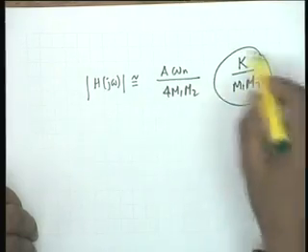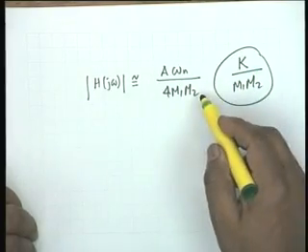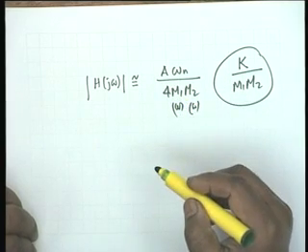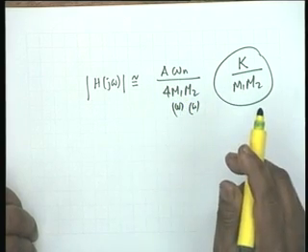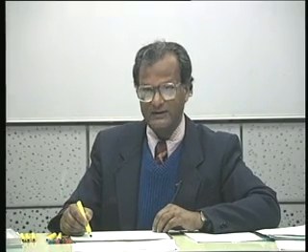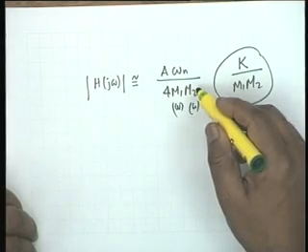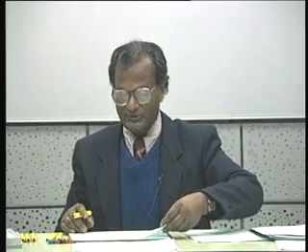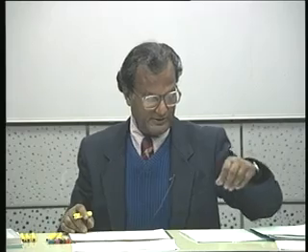In single tuned also the magnitude was k by m1 m2. Here also it is m1 m2. m1 is a function of omega, m2 is a function of omega. The only difference is that instead of the center point at origin, here the center point is at omega n, and therefore all the concepts of peaking circle should be valid here also. Okay, let me show a typical situation.